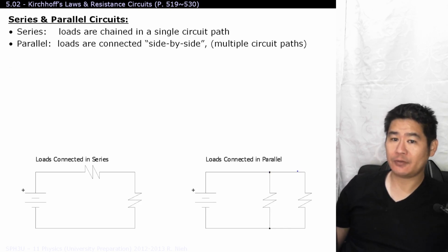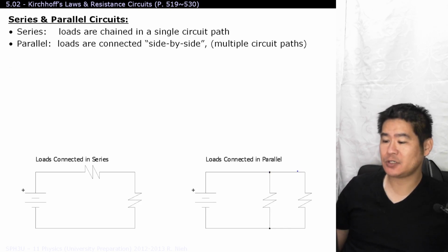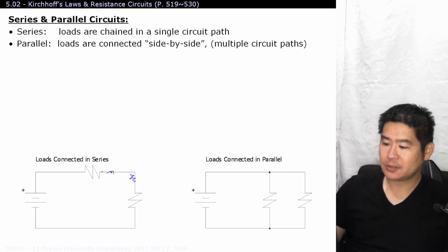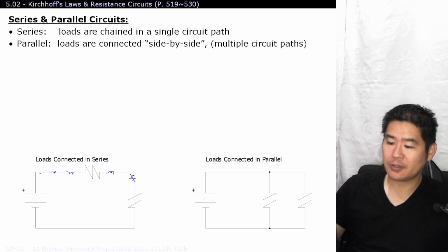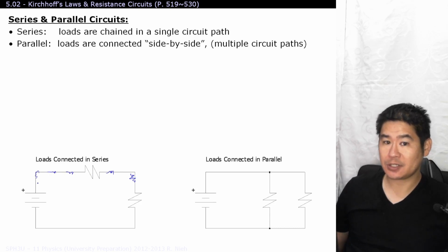These two circuits have their own corresponding advantages and disadvantages. For one thing, with regards to, let's say, Christmas lights, each of those tiny little bulbs cannot handle the 120 volts coming from your mains. That voltage is too high and it'll cause the bulbs to burn out. So instead they want to share that voltage, and that's why tiny little lights are connected together in series. So each one takes a small portion of the big pie.